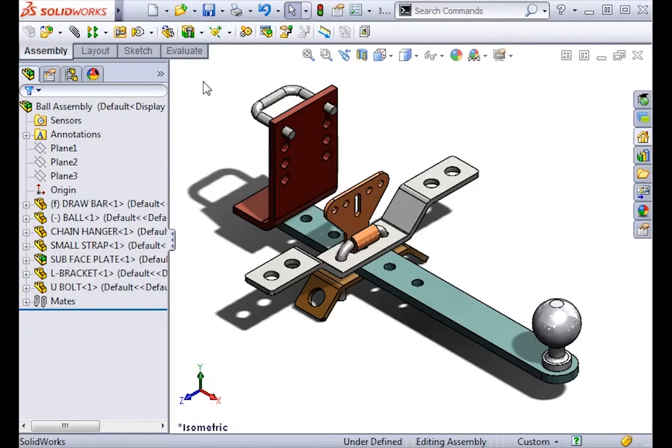When working with assemblies, you have the ability to reload components. This allows you to replace components if you need to do so, or simply change the way they were loaded in the first place. For instance, if you work in an environment with other SolidWorks users, you may find yourself working on the same assembly as someone else.